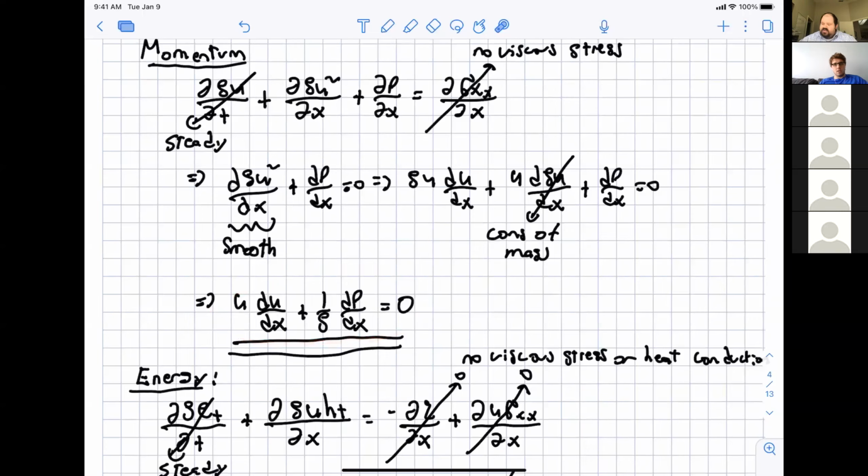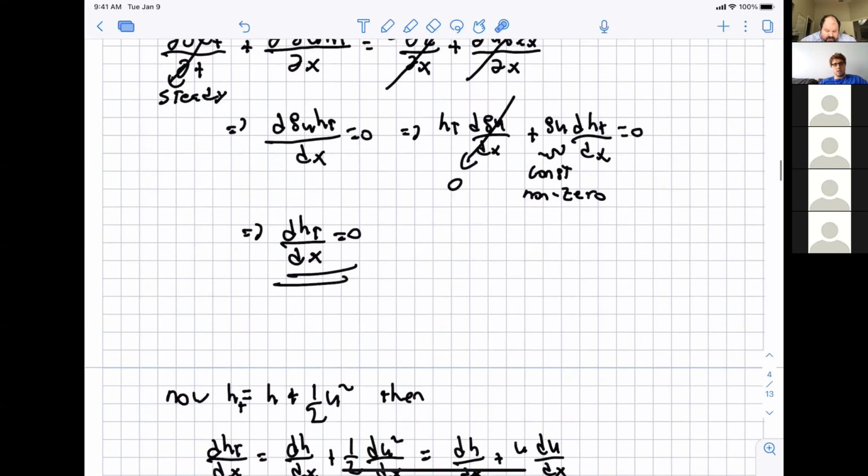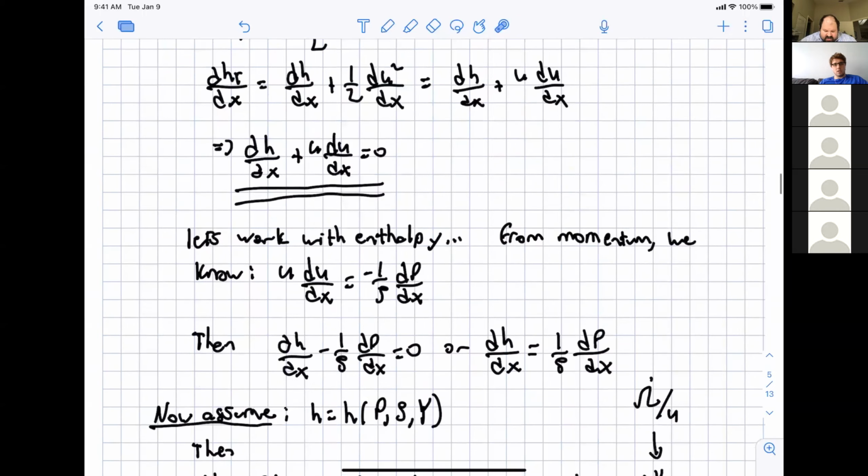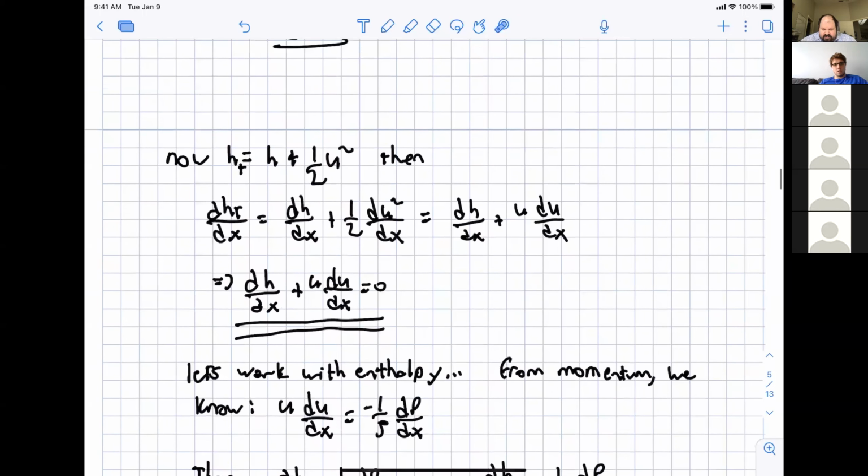But what we're trying to do here is transform these equations into versions in terms of which you can explicitly find dp/dx and dρ/dx and du/dx by themselves. If we can do that, we don't need the equation of state quite as much. I mean, you still need it, but the system sometimes becomes a bit simpler to integrate. And also you learn a lot more by doing that.